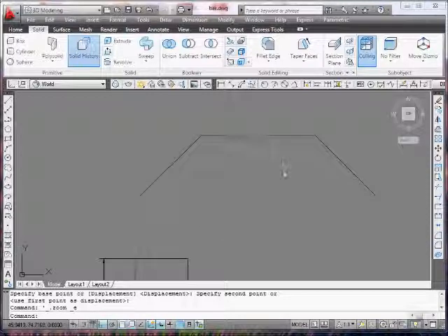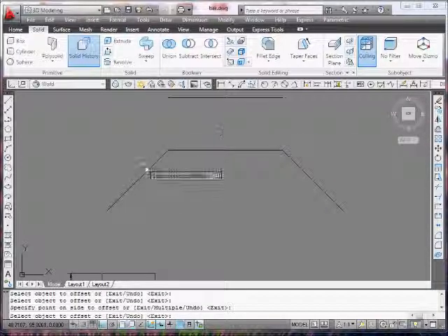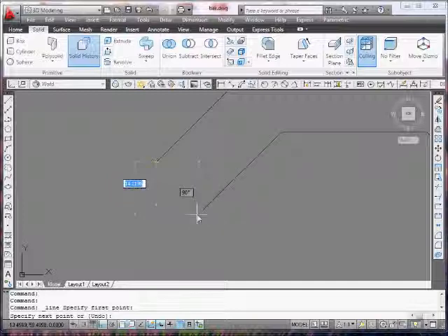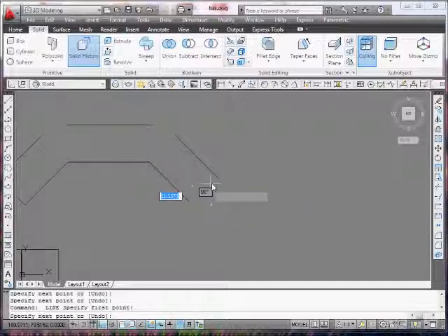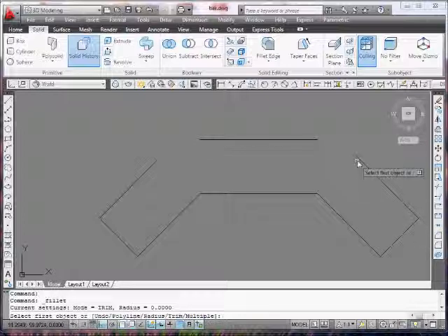And I'm going to offset them by 22 inches for the depth of the cabinets. So I go offset 22. This may be a whole review because it's all 2D, but it helps. Plus, some of you may not be the best at 2D, so this is some good practice.